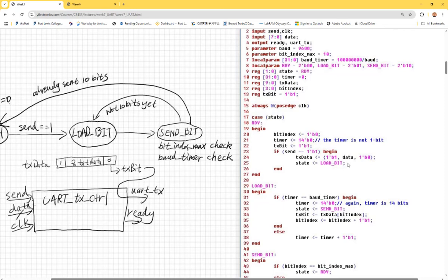And just send it out, right? Just send it out one by one, starting from LSB. You're sending LSB, it's a 0, boom, put it down, starts. Okay? Make sense? So this one doesn't have a parity bit.